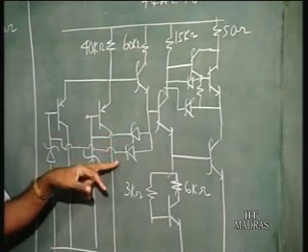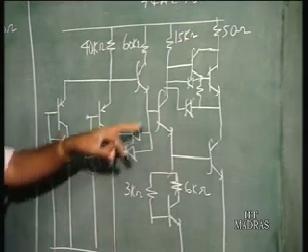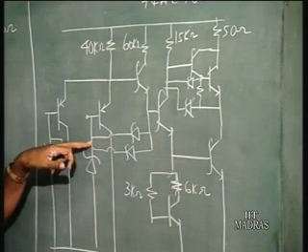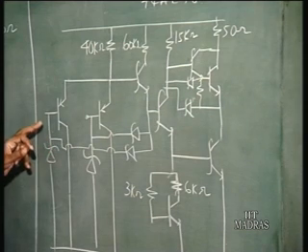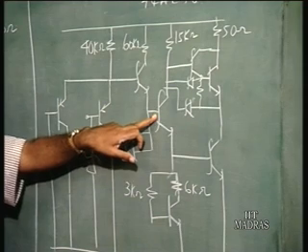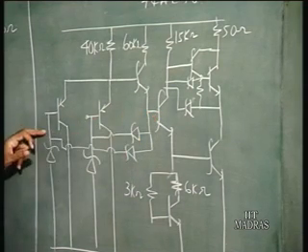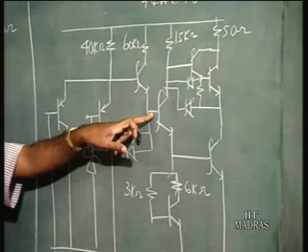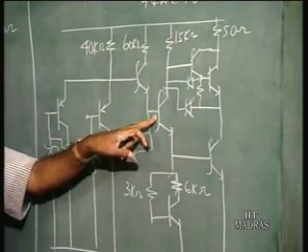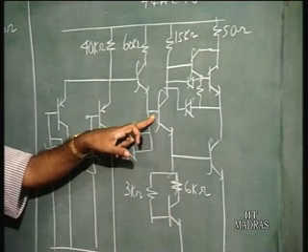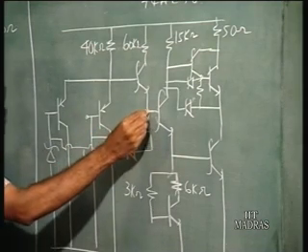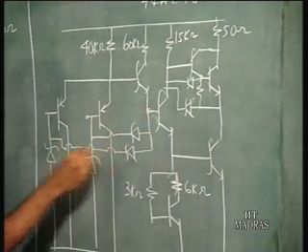You also have some additional diodes, you see here. This point here, the base of this transistor, is connected to the two inputs, so that when any input goes low, this transistor will be switched off. This transistor must be switched off fast. So when this input goes low, it has a direct connection to this point. So this base charge can be removed, and this transistor can be switched off. The voltage here is going to fall very fast. So that is why you have diode connections from this point to both the inputs.